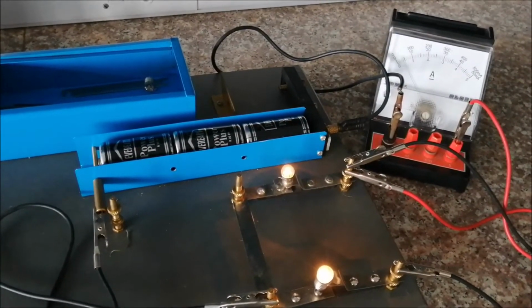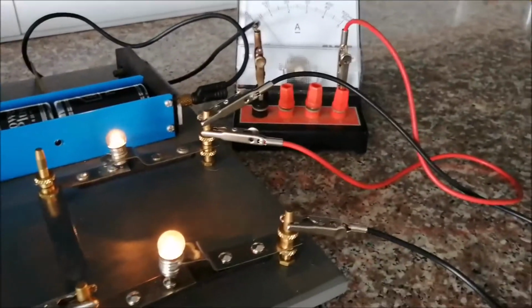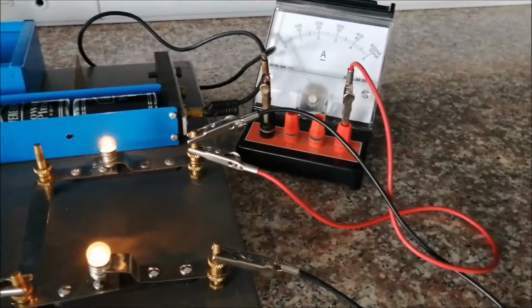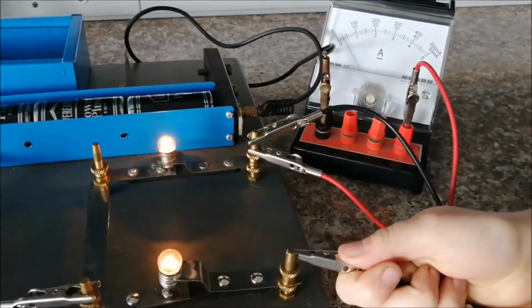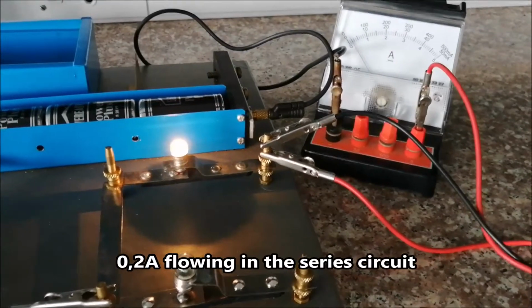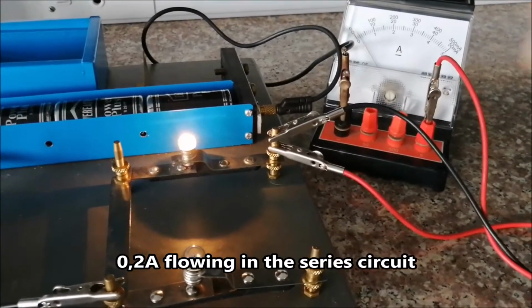Okay, and now let's have a look at the reading on the ammeter when we do the same thing. Let's disconnect the black lead. At the moment we've got, call it, 0.4 of an amp, and when we disconnect it and make it a series circuit with only one globe, just like we had before, we've got 0.2 of an amp.